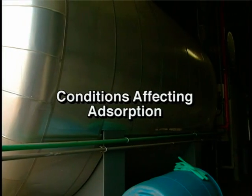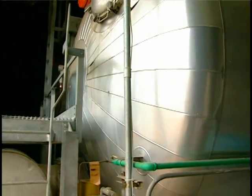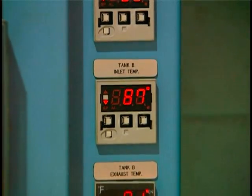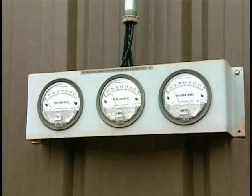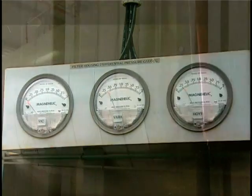At lower temperatures, the retention of the organic contaminant is highest. Because of this, carbon adsorbers are usually operated at temperatures less than about 125 degrees Fahrenheit. The low retention at higher temperatures provides one method for regeneration. At lower system pressures, retention is lower, providing another method for regeneration.